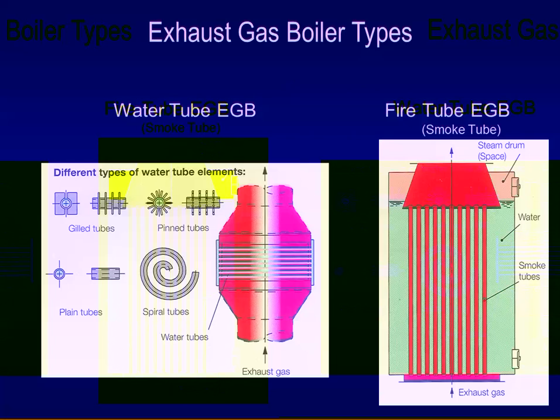And the thing about this too is if you were to get into a metal fire in the exhaust gas boiler, so much material would be dropping down from that fire and most likely would get into your turbochargers. It would be very difficult for me to see where you would be able to get underway if the fire was that devastating.